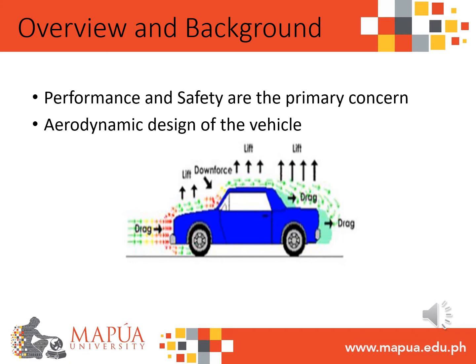When a vehicle is moving, various aerodynamic elements are experienced by the car, like the drag, lift, and the downforce as seen in the figure. The drag force acts horizontally and competes against the forward motion. For the lift force, it acts vertically where the pressure under the body of the vehicle is observed. Proper aerodynamic lift force is observed to increase the stability and handling of the vehicle. When the lift force is greater than the downward force, the vehicle moving would be prone to accidents.